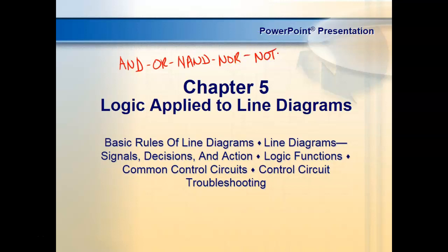We're also going to look at 2 combinational logic that we refer to as exclusive OR and exclusive NOR. Those are used a lot in relay. So we call this relay logic. A lot of people will call a ladder diagram, they call the circuits actually relay logic. And that's when we decide how we can hook contacts to perform these 5 basic logic gates, and then how we hook contacts to control the combinational logic. Combinational logic means we do a combination of this, right?